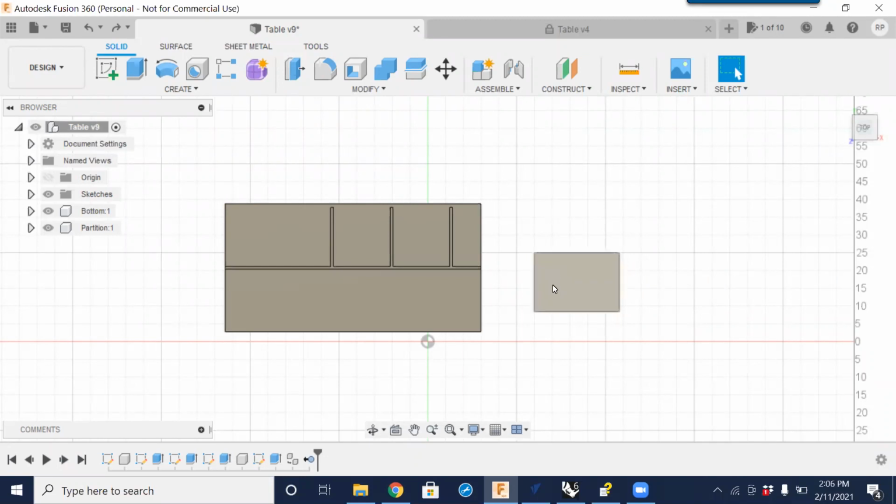An example of that is we are going to end up making this component fit into this dado here. And when we move that, if we don't have one of these two objects grounded, things are going to get a little wonky on us, where the bottom might flip upside down to fit here and vice versa. So we really want to start off with one object grounded. For those that are coming from SolidWorks, Inventor, and that type of software, it's just locking that position in place.